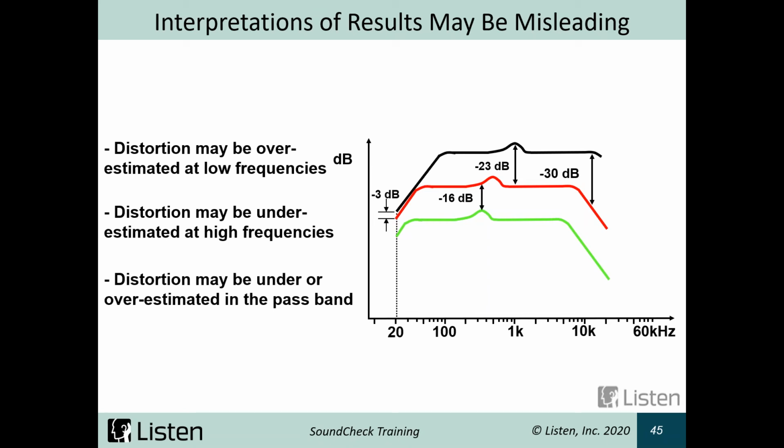In the passband, it's going to depend on the exact frequency we're talking about and the exact response of the device under test, but you could be over or underestimating the distortion, depending on where some of the peaks and valleys are in the frequency response and amplitude linearity.